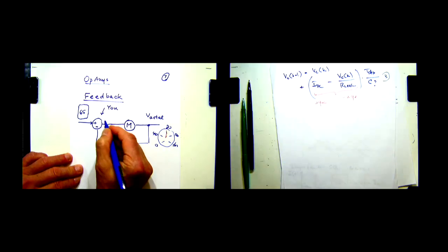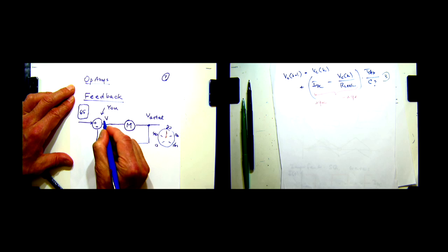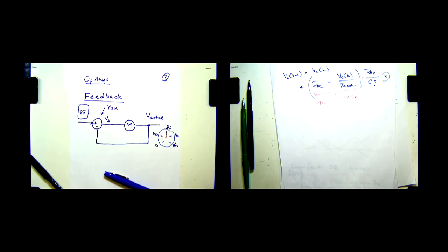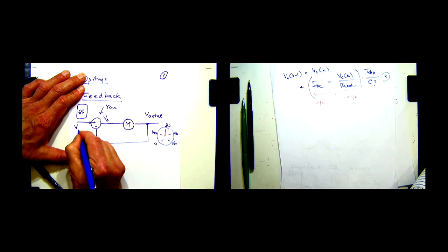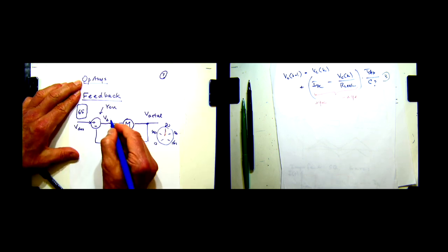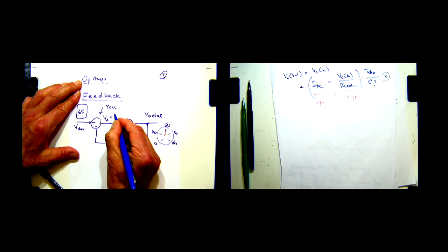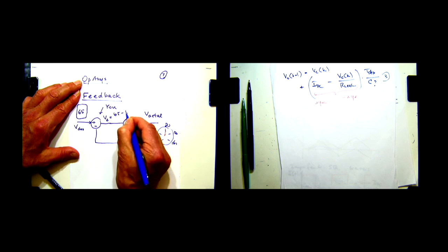You say, oops, I'm going too fast, and you let the accelerator pedal go a little bit. So basically here you calculate the difference, V delta, which is the desired speed, V desired, minus the actual speed. You calculate that difference. If that difference actually is negative, in this particular case, it would be 80, it would be 65 minus 80. Well, then that means you have to remove your foot from the pedal, okay?